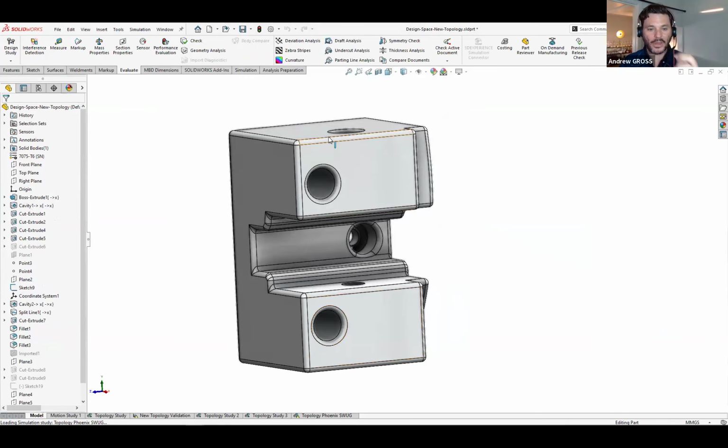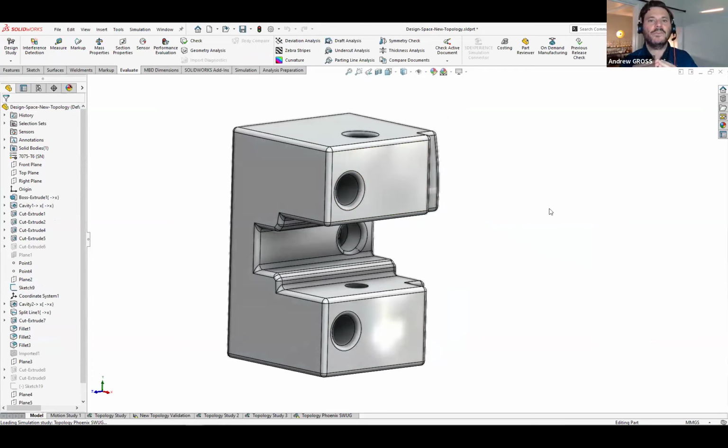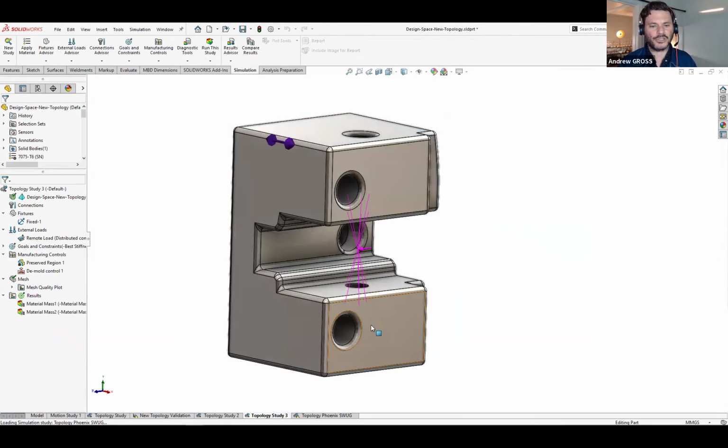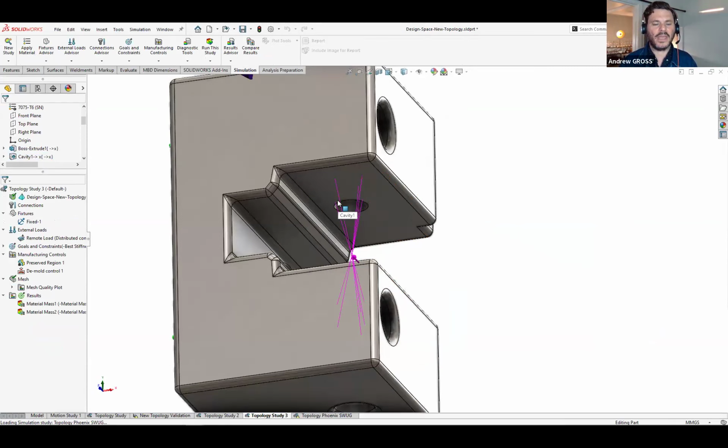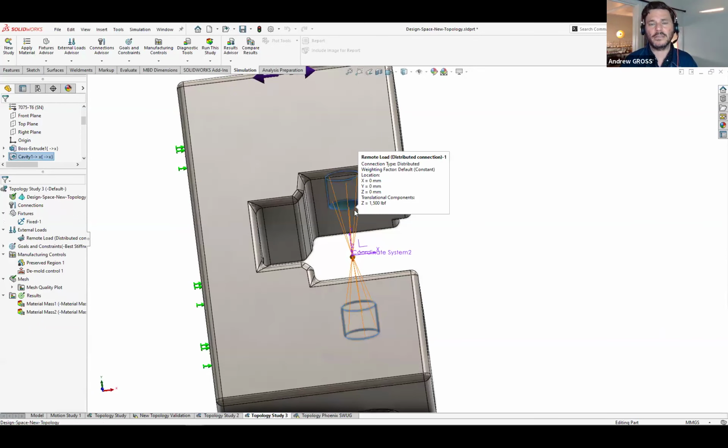But as we know, a lot of times in FEA, having infinitely sharp corners, because anytime you don't fillet something or put a chamfer, if that corner is sharp, sometimes you can get something called stress concentrations there. Honestly, in this case, I don't think it would make any difference at all, because really what the solver is doing is a subtraction technique. It's understanding the energy profile of every single element inside.